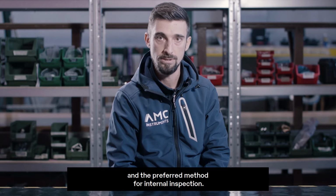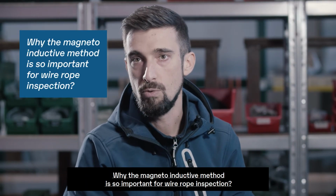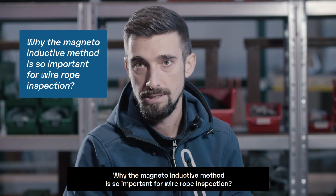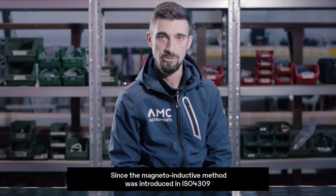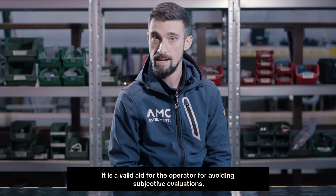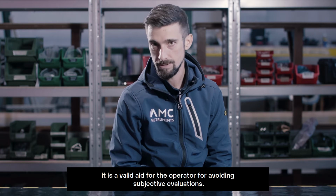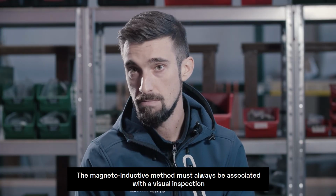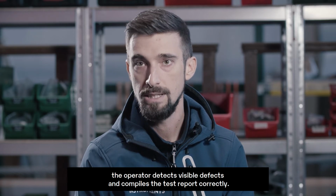internal inspections. Why is the magneto-inductive method so important for wire rope inspections? Since the magneto-inductive method was introduced in the ISO 4309, it is a valid aid for the operator for avoiding subjective evaluations. The magneto-inductive method must always be associated with a visual inspection.